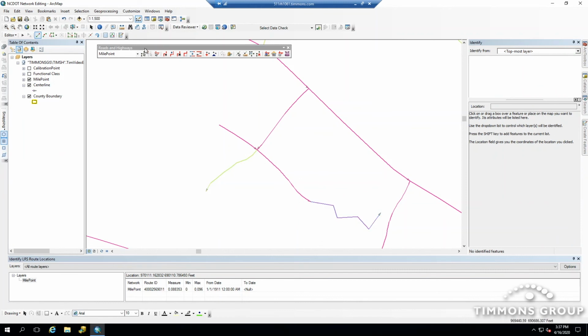And then from the Roads and Highways toolbar, we want to choose the centerline, not to be confused with selecting the centerline. The choose centerline is a separate activity altogether. Once the centerline is chosen, it turns blue, and it gets a label applied to it that tells you which number in the chosen centerline set it is. In this case, I'm only choosing one centerline, so it's going to be number 1. If you wanted to choose more than one, they will be numbered 1, 2, 3 in the order that you chose them.